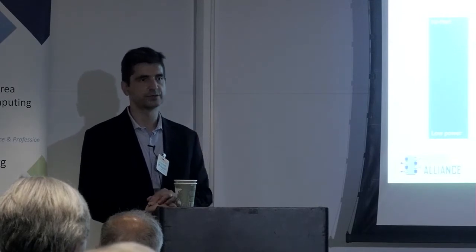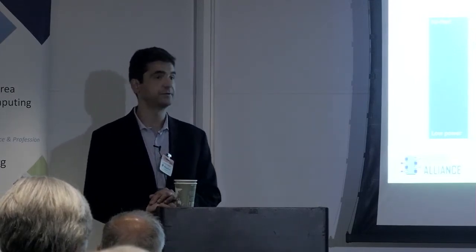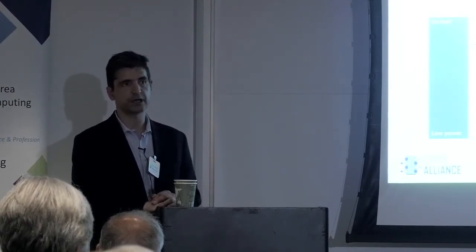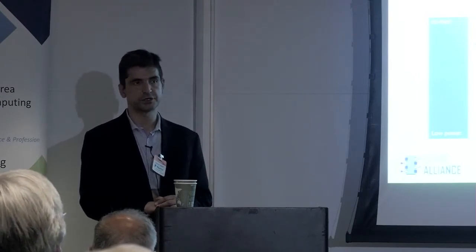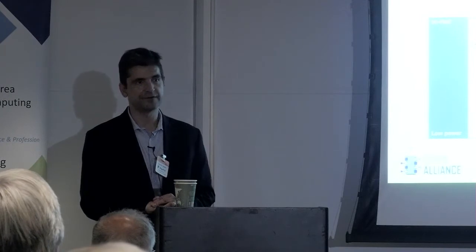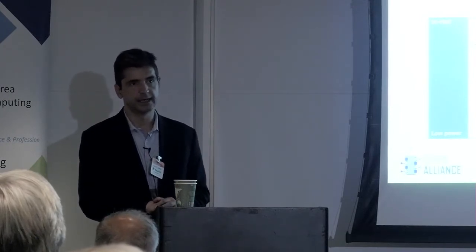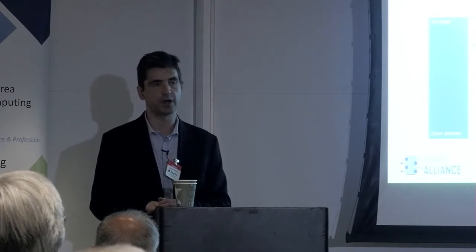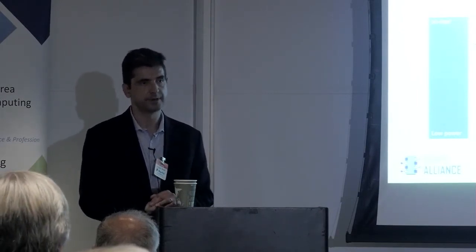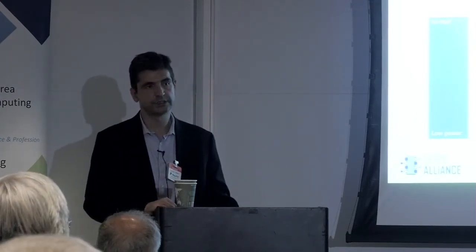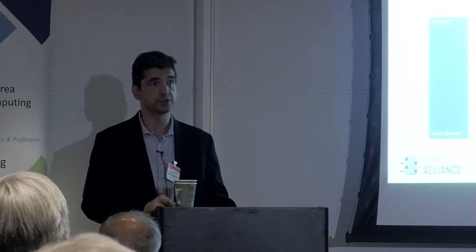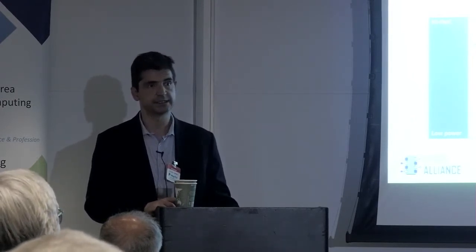The cores are obviously available as is under the Apache v2 license. The methodology that has been used is the tribal knowledge of verifying compute cores. And we typically have internally 3 release cycles that we call alpha, beta, and gamma. In each cycle, several billion instructions have been run through our COSIM environment. The instruction set simulator that was used as a golden standard in our COSIM has been open sourced. It's called SweRV ISS, and it's available.